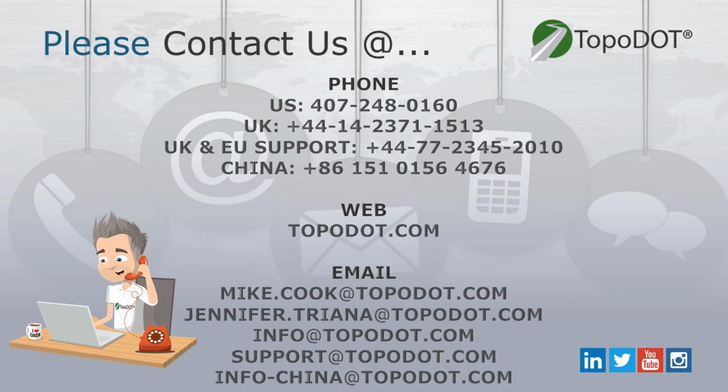Great job, Mike. Well, we did have a couple of questions. A few people asked whether these tools can be used with other scanners, like static scanner or UAV. And it can be, as long as the data matches the requirements that Michael was talking about: basically the coverage, the data noise level, the density. So if you can achieve that type of quality with your point cloud, then you can apply it to any other system, not just mobile laser scanning.